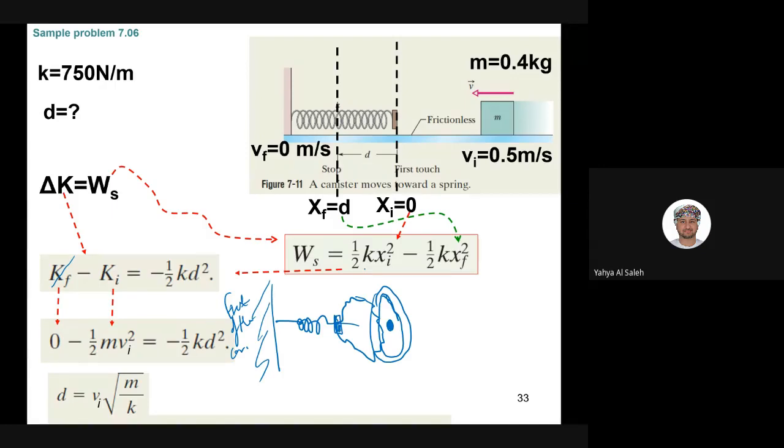Now, here you have some chemical component and some pyros that get activated. If you are in a tiny accident, the compression is quite low, so nothing happens. If, however, you are in a rather bigger accident, the damage is more, the force is more, so this thing compresses even more.